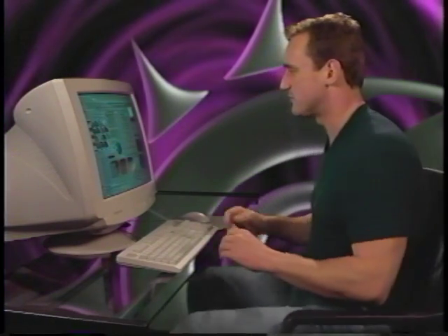For example, if you have a character standing behind some thin paper wall that's backlit, then you would actually see that shadow from the back side. Okay, so your camera's looking here at the surface, an object in the back here would cast a shadow onto this surface, and you'll see that inverse shadow on the other side of the wall. That's the translucency setting. So that's a real handy thing to have.